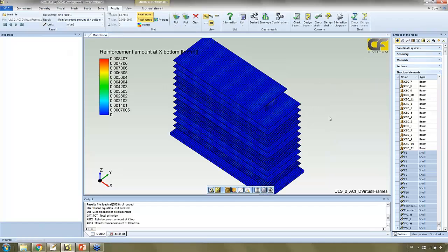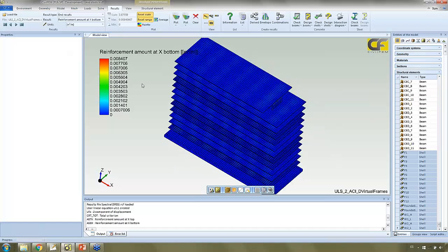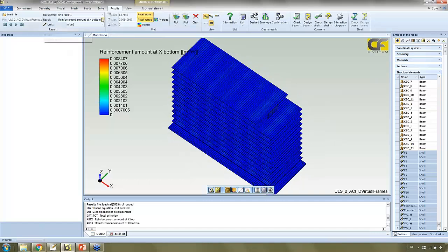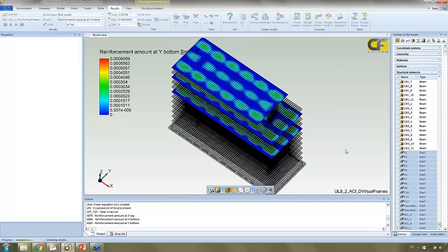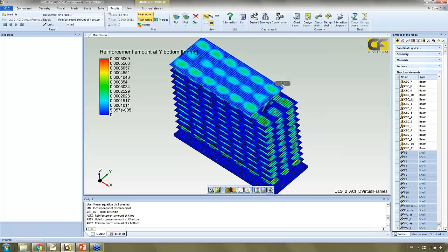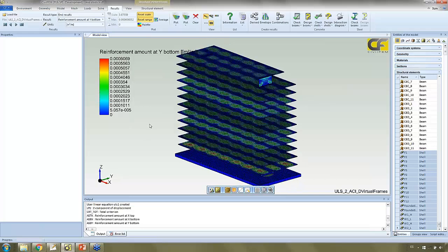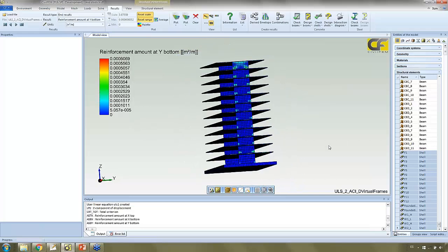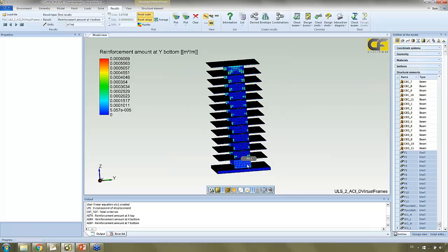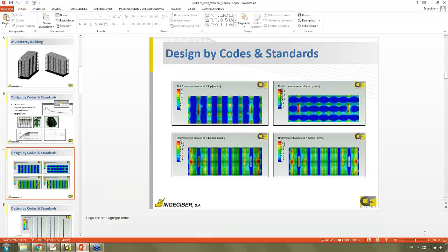Now also shear walls mainly, and also for Y direction, bottom. Here we can see also in the slabs we need reinforcement. This is the reinforcement we need. Mainly what we've seen is that the most important points are the shear walls and the column beam connections. So we can study in detail those parts with nonlinear analysis.